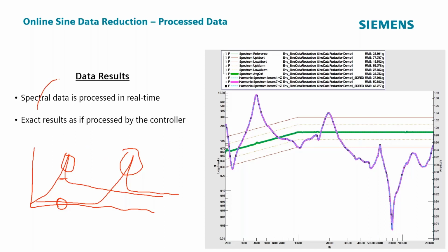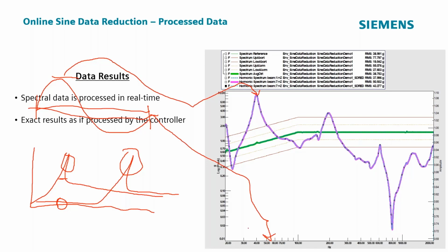So that's why we have this time domain method where we're looking in the time domain. We figure out what this frequency is, what this amplitude is, and this gets plotted at whatever frequency this is. Yeah, we can kind of grab those peaks individually. You grab the peaks individually, exactly. I mean, essentially what you're doing is you're applying a bandpass filter constantly to the incoming time domain stream. And as that frequency changes, just plotting the results of that bandpass filter per amplitude.